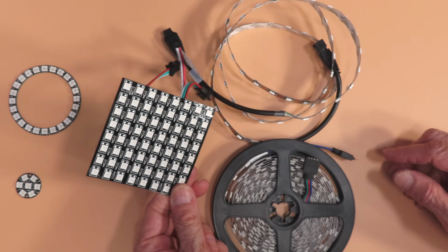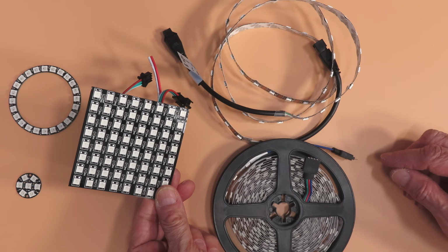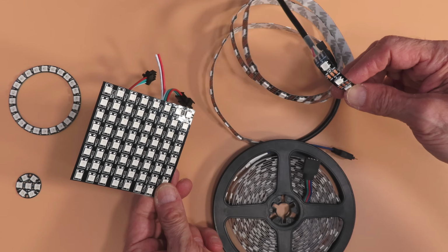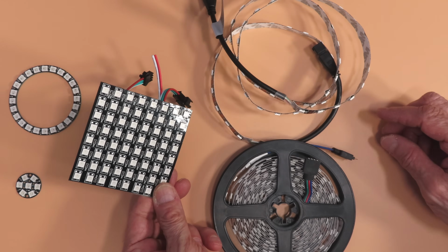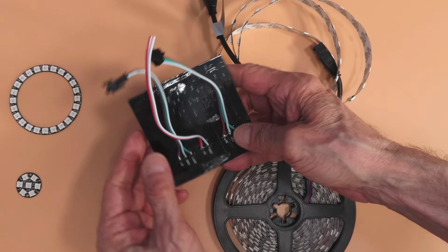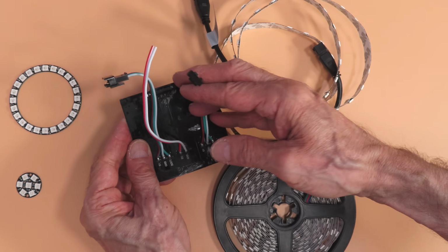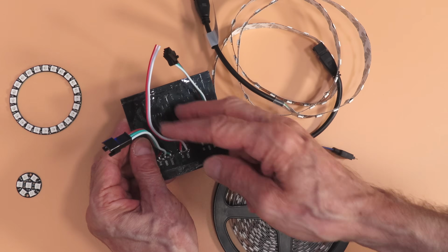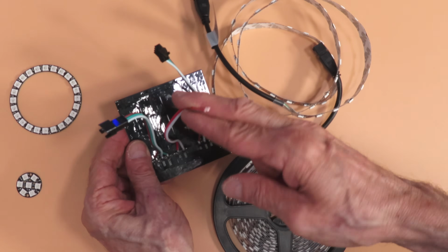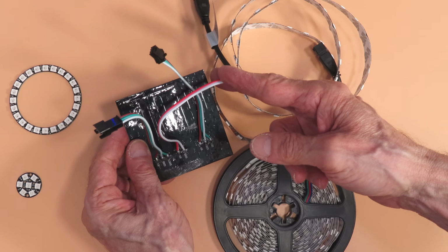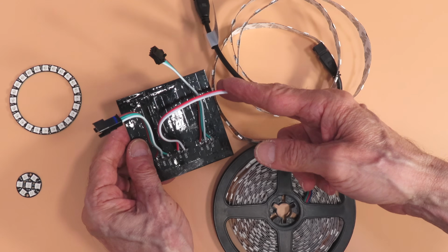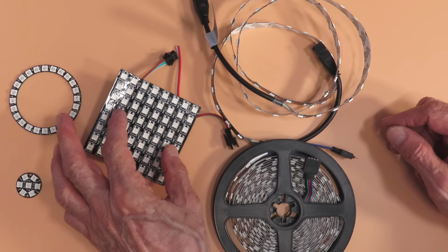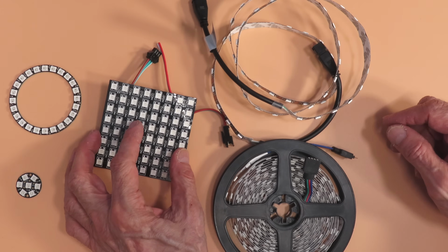This is an LED matrix, and it's got 64 LEDs, and it can also be used with WLED. It's basically just like this. It's the same NeoPixels, except there are 64 instead of 60 of them. If we look on the back of them over here, you can see you've got the connector here for the input. It'll cascade, so you've got another connector in the output. And they also bring out a power connector over here, and this is if you want to do something called power injection, and we'll talk about that in a little while. It's a way of adding extra power to large LED displays. And we're going to take a look at this matrix display a little bit later as well.